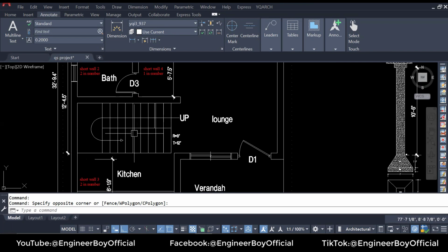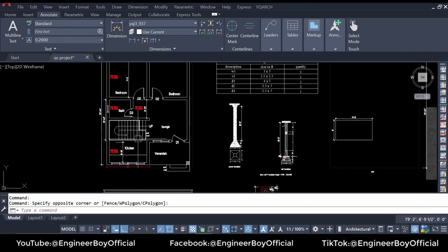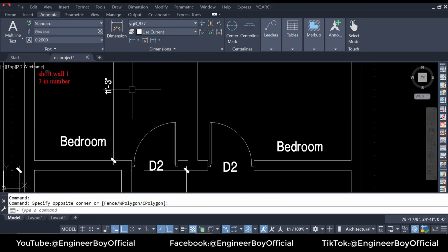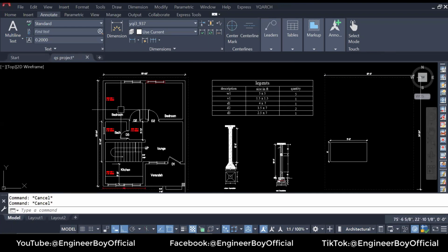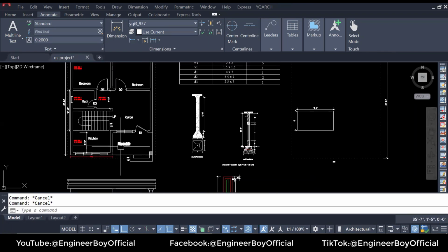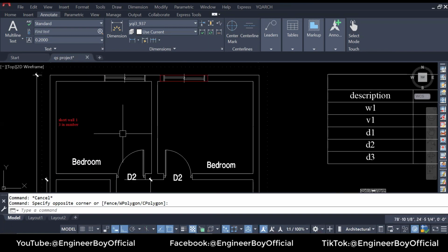Let's say if we have plaster work, we will take the stair at the end, no problem. So let's see, we have the plaster work, and the plaster work can be internal and external as well. So let's focus on the external first. We will take the parameter of the wall, and then multiply that with the height of the wall. You can even do that with the long wall, short wall method. If you have long wall, short wall, you can apply that method as well, no problem.